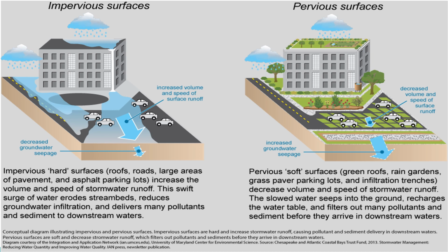This diagram here goes to show you the distinction between impervious and pervious surfaces. Essentially, if the water can't go down, it will go through. And when we have these large concrete and asphalt areas, that can result in water damage to buildings. It can result in mold and mildew and flooding. But with pervious surfaces, we give that water an opportunity to go down instead of through.